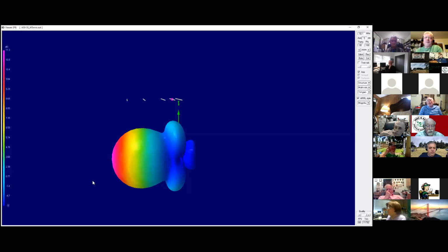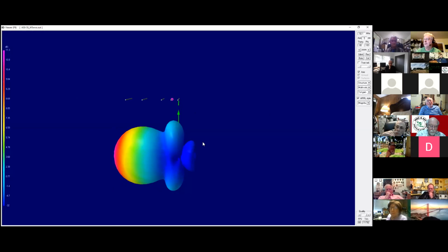I'm curious, did this offset the radiation pattern at the axis versus the elements of the antenna? It just caught me off guard. Usually doesn't it center it around the elements of the antenna? Yes. Now you might ask me, why did you do this, Scott? I did that so you could actually see the antenna and you can see its pattern. Okay, now I understand. That's why I did it this way. If I showed you the dipole model, it goes right through the middle and you see the donut. But I wanted you to get a feeling for the antenna and a feeling for the pattern. Now the pattern is the far field pattern, so it's not tied to the position of where the elements are on the picture.